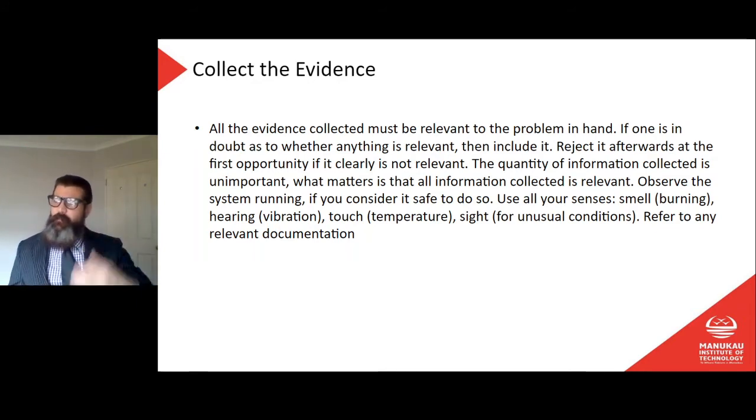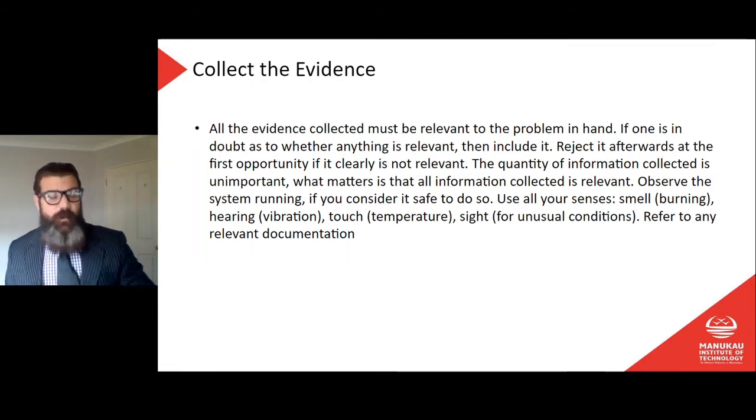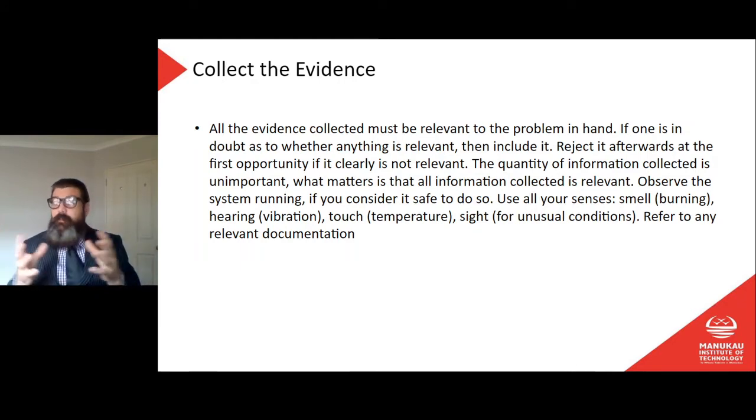So then your next step would be, well, where are those 6 lights switched from? Oh, they all come from the same switch. Okay, that's where I'm going to go first, right? Logic. We need to use some basic logic here. Look for your point of commonality.